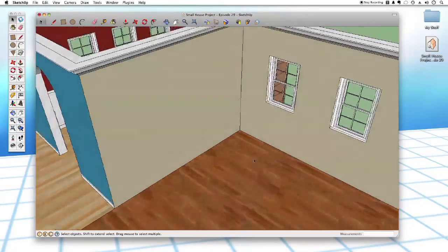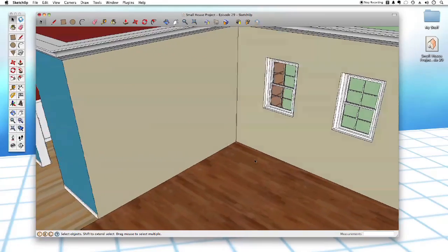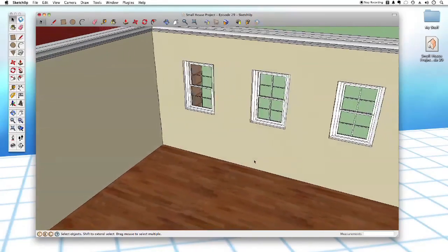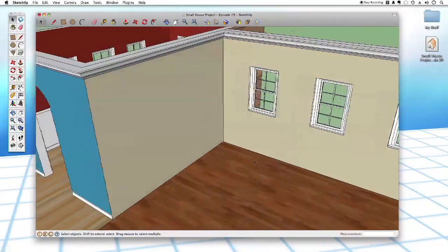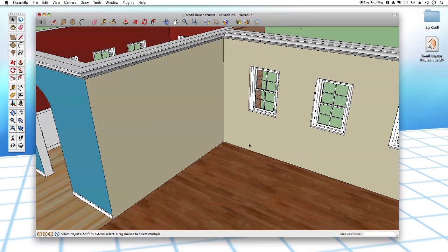Now, one thing that's very important to point out is that when you're building things like cabinets or even just any kind of furniture, it's a good idea to go online and research the typical dimensions, or if you have cabinets in your kitchen, measure how high they are, how deep they are. In my case, I just did a quick Google search and I've come up with a couple of very simple dimensions. 3 feet high, 2 feet deep, and each cabinet unit is 2 feet wide.